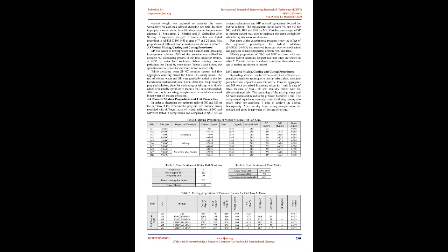As can be concluded from the available literature, there is no clear range of the optimum NC ratio to be added to concrete mix. Moreover, numerous researchers studied the effect of adding only NC on the performance of concrete. Therefore, the hybrid use of NC and MP is implemented in the study. This technique of using hybrid additives in producing concrete mix is suggested by the authors to reduce the amount of NC additive in the mix. This reduction would lead to also minimizing mix cost besides its environmental benefits. Also, effect of various NC dispersion techniques on mix mechanical properties is studied to overcome agglomeration problems.